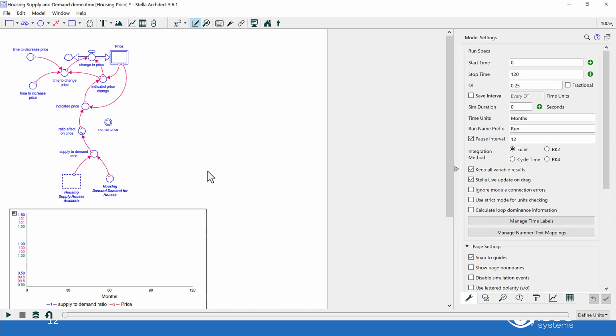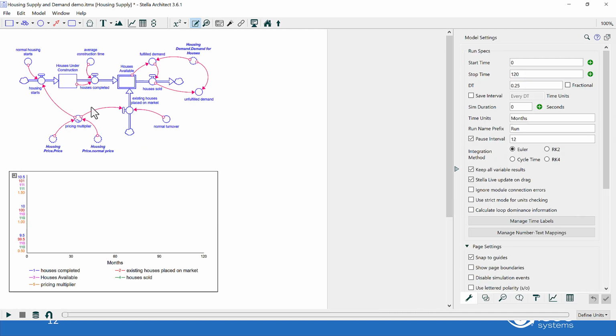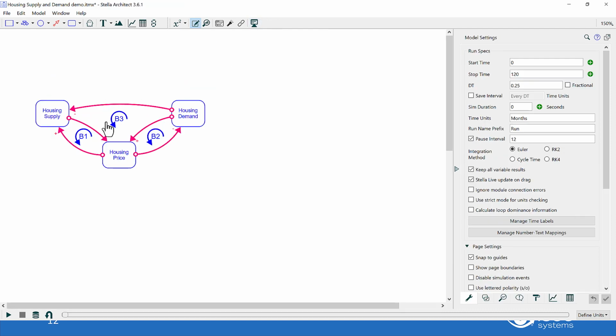So that's the fast way to connect things without having to set module input, module output, or anything. And when you do that, it creates connectors if they aren't there. Notice it did make this a module output again. So far so good, right?